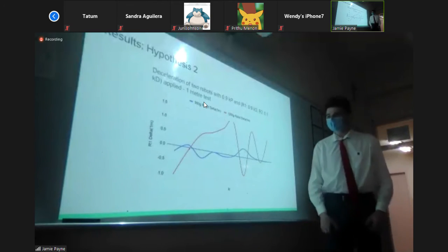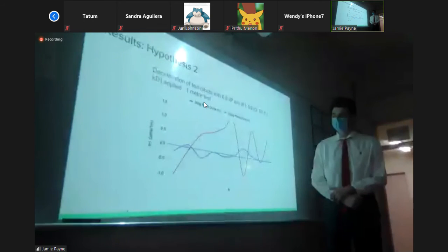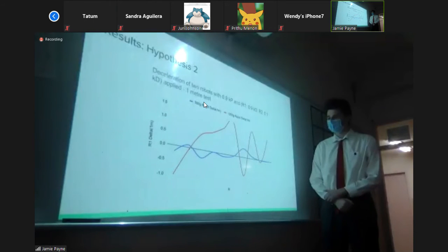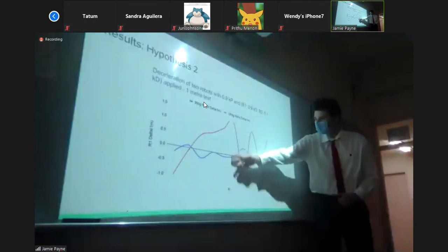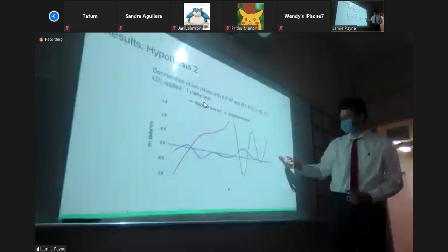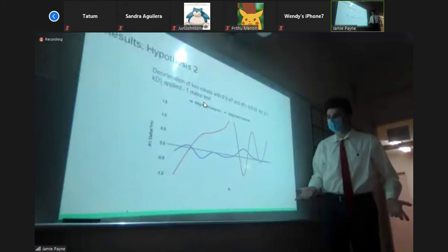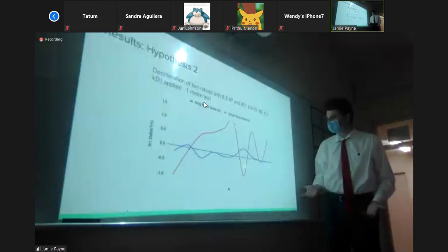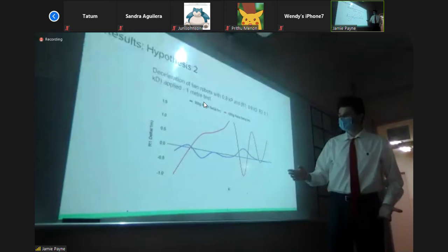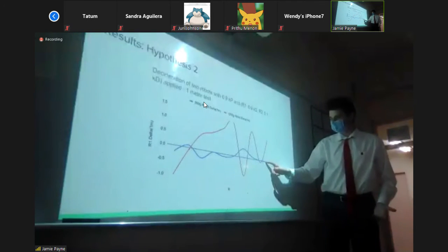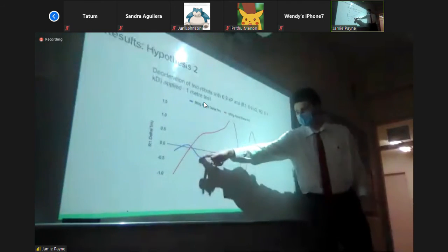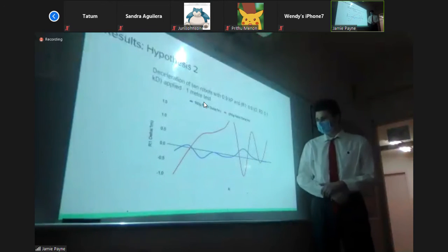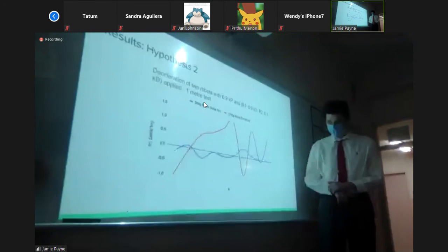Now, what didn't make sense is the integral, because the 1200 gram robot just took off. It started to overshoot all over the place, and that's because of the integral component. We know why that happens. But the 900 gram robot did a fairly decent job of staying at the same destination, so to say. But yeah, the 1200 gram robot just sucks.